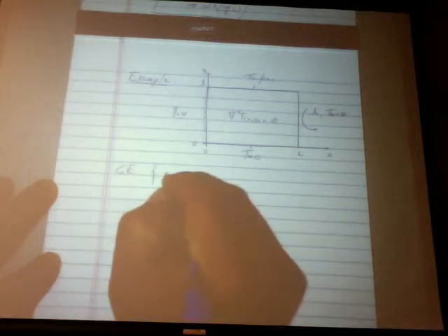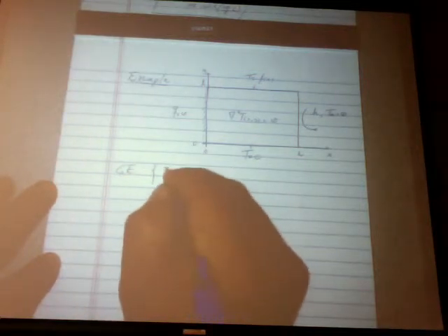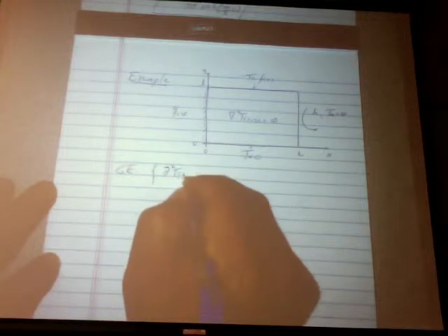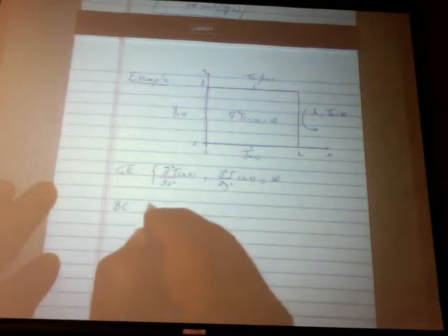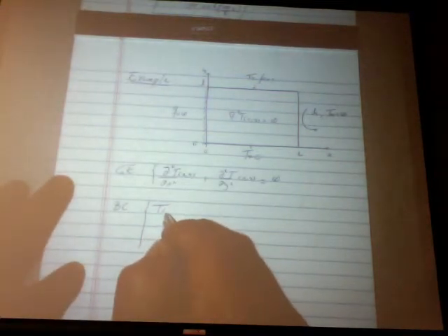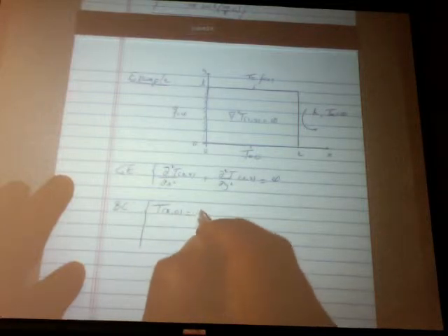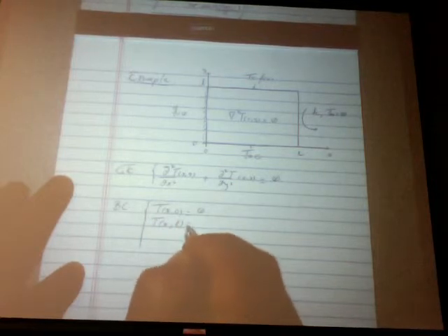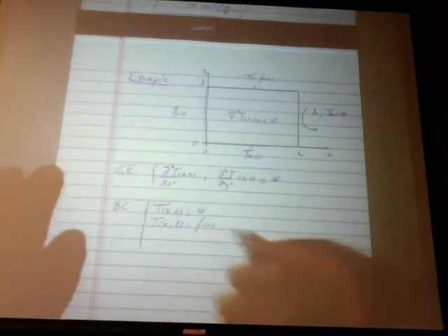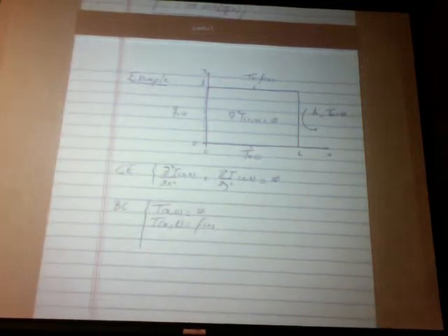Mathematically, this will be the Laplacian of T equal to 0, that's the second derivative of T with respect to x, x, y, d x squared, plus the second derivative of T with respect to y squared, x, y, is equal to 0. And the boundary conditions, let's start with the boundary conditions in the y direction. Those are the easy ones. The temperature at x, y equals 0 is equal to 0. The temperature at x, y equal L is equal to some f of x. Those are first kind and first kind conditions.